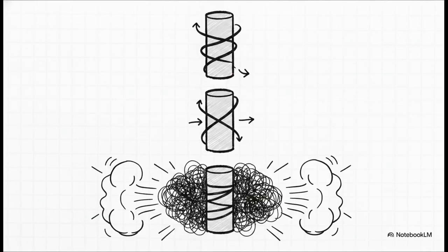But here's the catch. An elastomeric core is often way too exposed or sensitive on its own. So what do we do? We cover it. We can wrap it once for a single covered yarn, wrap it twice in opposite directions for a double covered yarn, or, get this, we can literally blast it with an air jet to entangle protective filaments right into the elastic core for an air-covered yarn.